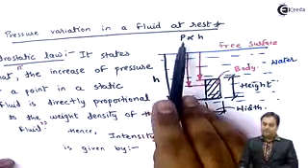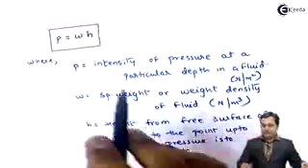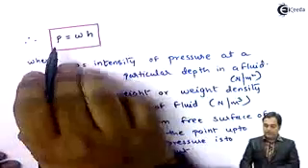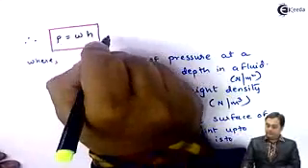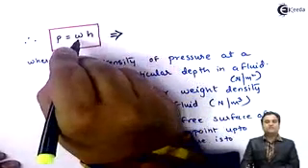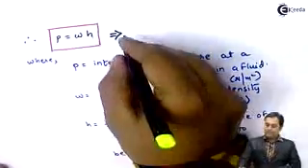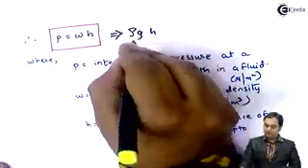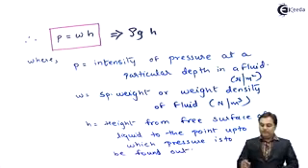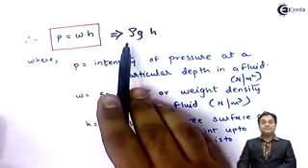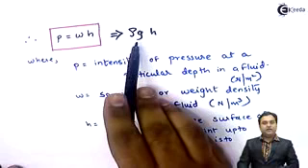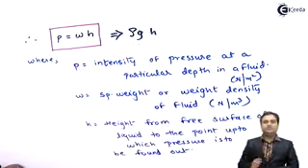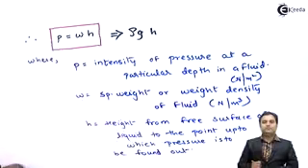So here we have seen that pressure is directly proportional to the height, and as I have written the formula previously also, intensity of pressure can also be written in this form: specific weight or weight density, we know that it is equal to rho into g. So the formula becomes rho g H. So even if we know the density, this density is the mass density, and we know the acceleration due to gravity, H is the variable. We go on changing the value of H, we would be having different values of pressure.